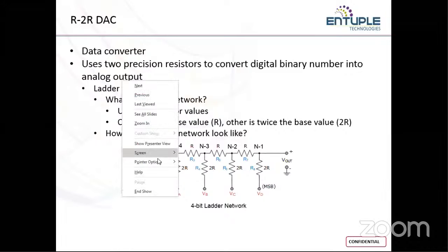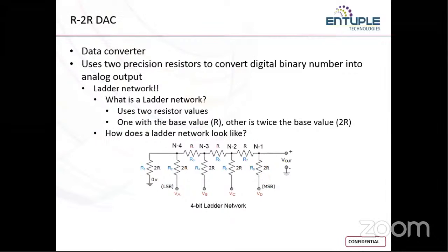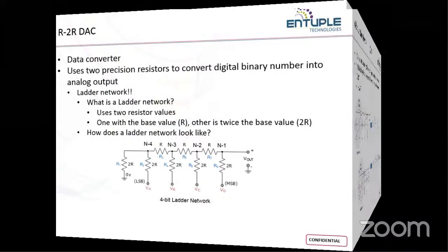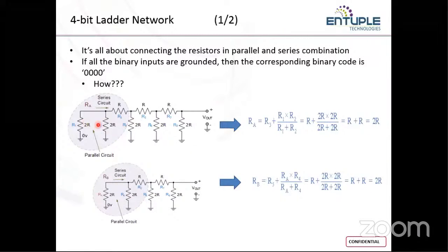What we have to do is measure the equivalent resistance all the way, and then it will look similar to a Thevenin's equivalent circuit, where a resistor is connected in series with a voltage source. That is what a Thevenin's equivalent circuit is, right? So that is how it's going to look. So how to do that? We have demonstrated it stage by stage. First, you see these two resistors are in parallel, right?